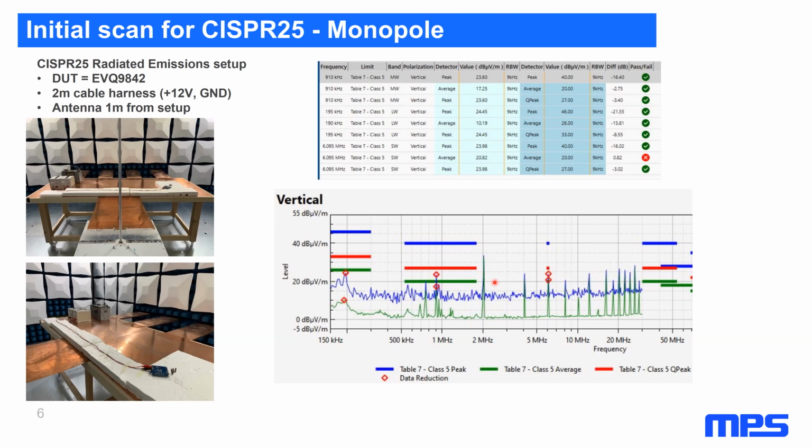which is obviously quite a few spikes here in this range between 2 megahertz and 30 megahertz. Note that all these are passing because there are no limit lines in this region or this region. However, at 6 megahertz, there's a specific limit line that we need to meet, which in this case, it looks like we're failing by a small margin. It looks like we're about 0.82 dB over. So it's marginal, but at any customer, this would be considered a failure. So here's one issue that we've found so far that we're going to have to deal with.